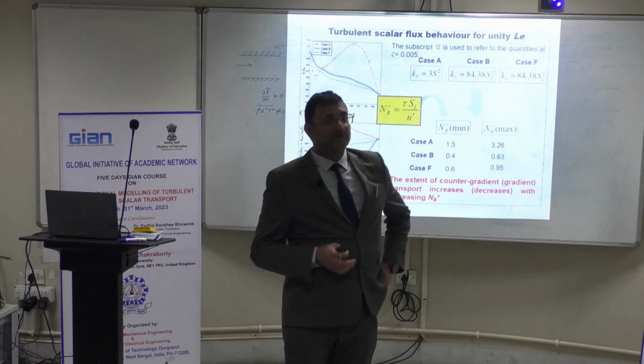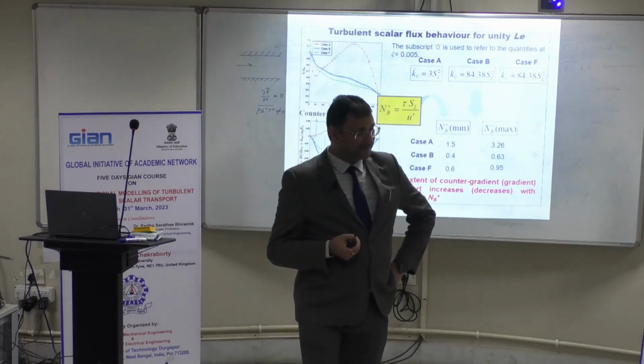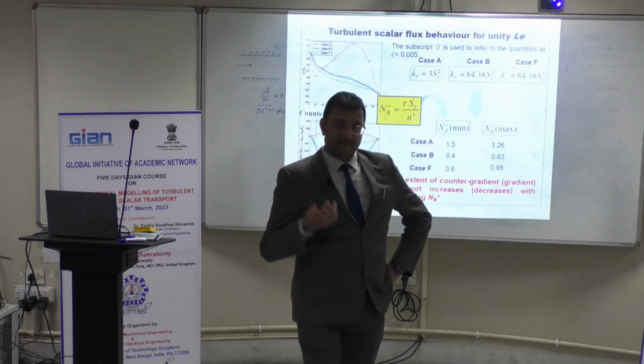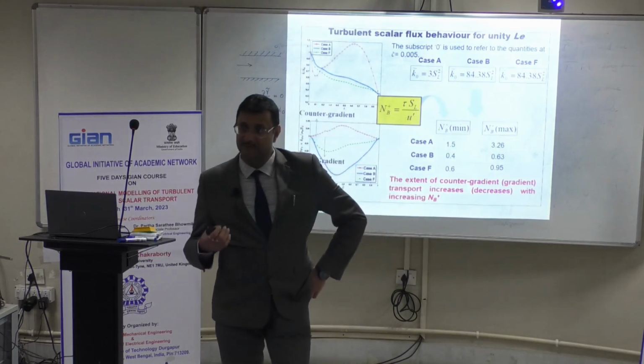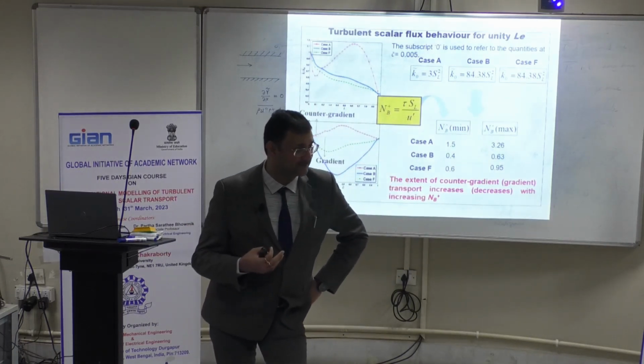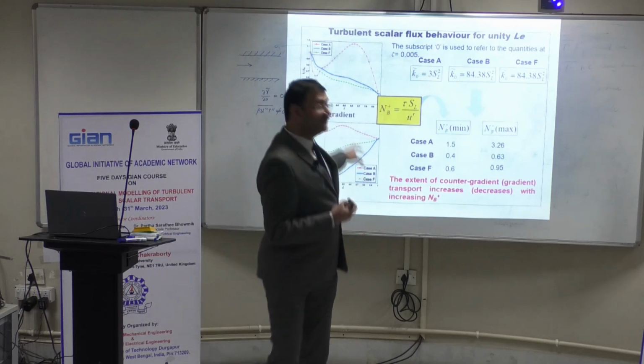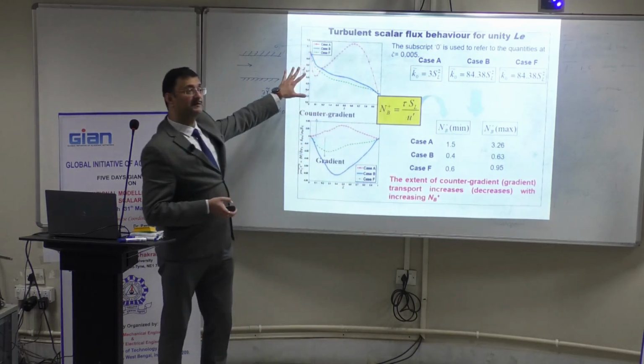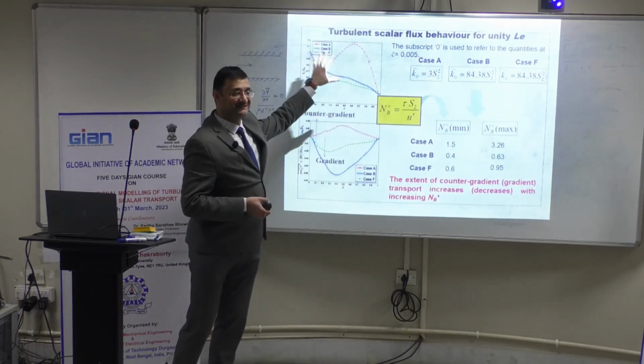Case H showed a considerable amount of counter gradient behavior. That means thermal expansion effects were stronger in comparison to the turbulence. And that effectively gave rise to a considerable amount of flame generated turbulence.